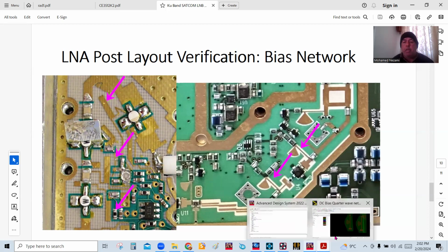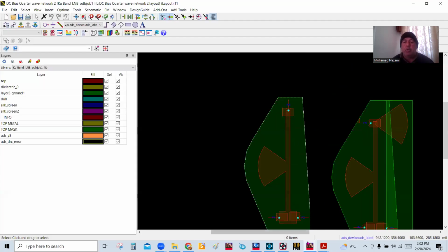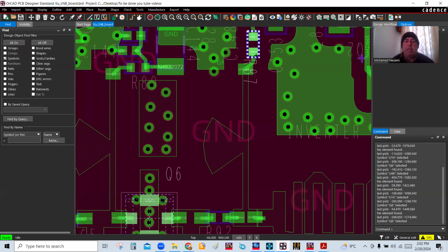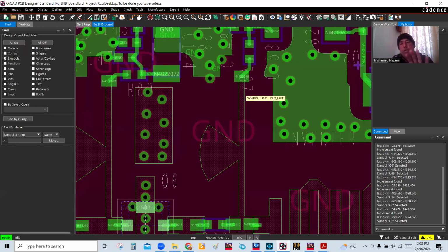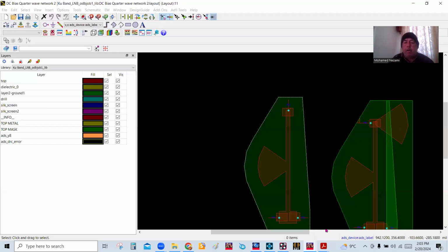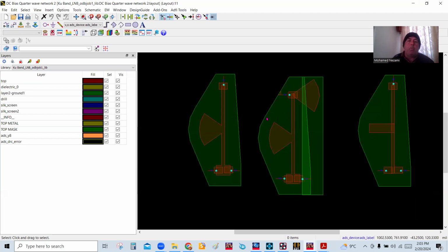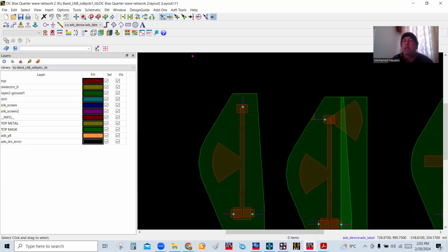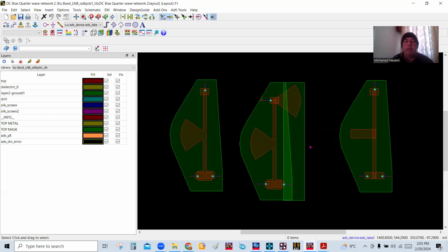In my case, I put an additional line in there. I could have put this resistor right here, because at this point the radial stub provides a short RF-wise. So whatever you do beyond this point really doesn't matter. But in my case, because of certain issues that had to do with this design, I had to extend another line in here, and we can talk about that offline, why that was special for that case. So whether this point is fed here or here really doesn't matter. Since this distance is the same as this distance, that's a quarter wavelength from here to here, and this is about a 100 ohm line, somewhere between 80 to 100.